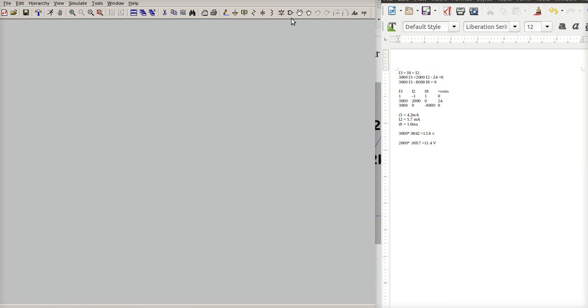So I'm going to use the Component tab. Here's my resistor. I'm going to use the label, the ground, the wire. When you first start doing this, you'll make some mistakes. So if you put something on your schematic you later on don't want, or if you're trying to follow me and I do something that I don't tell you about, then the scissors here is your friend. Anytime you turn on something up here, generally you have to turn it off, which is either right mouse click or hit your escape key on your keyboard.